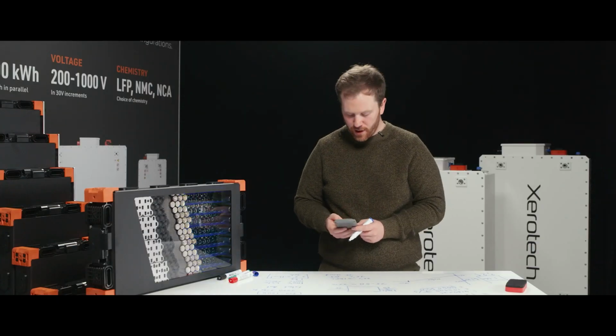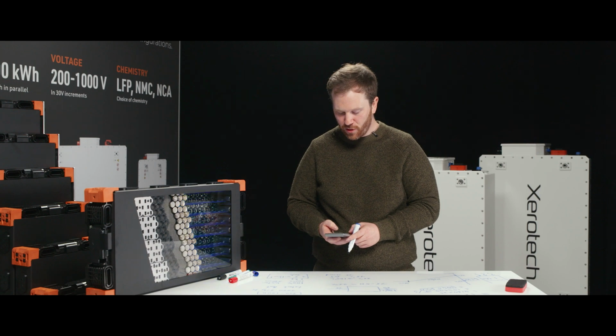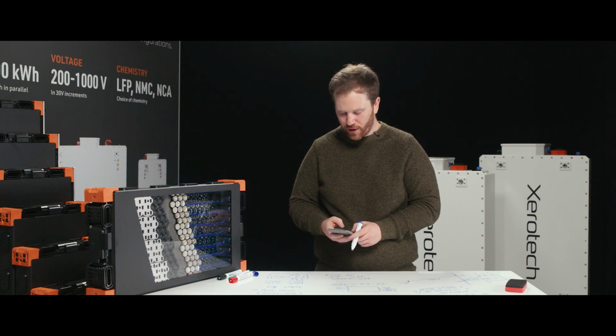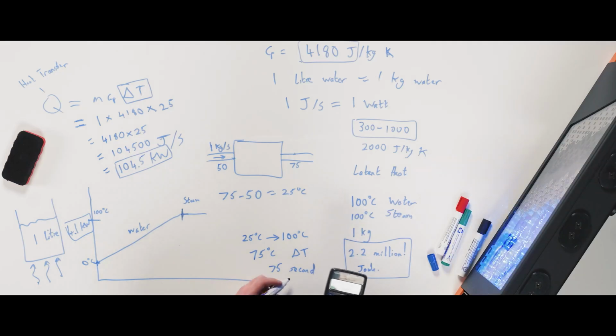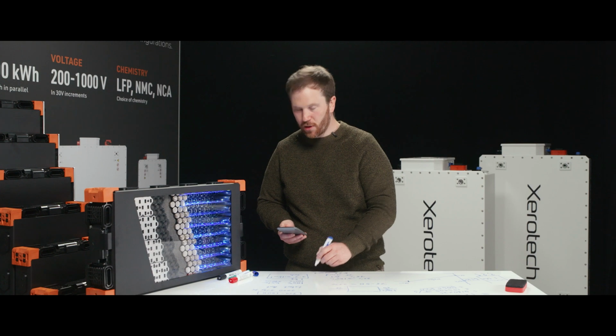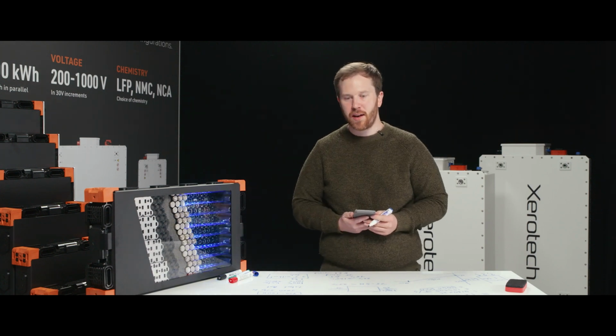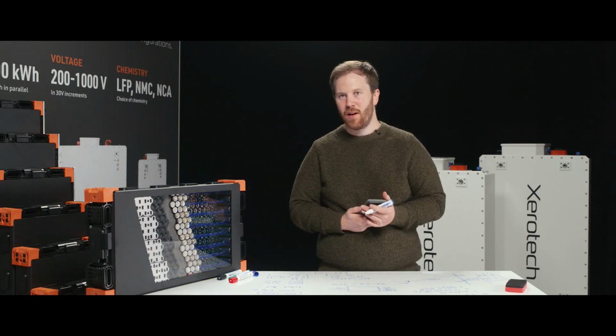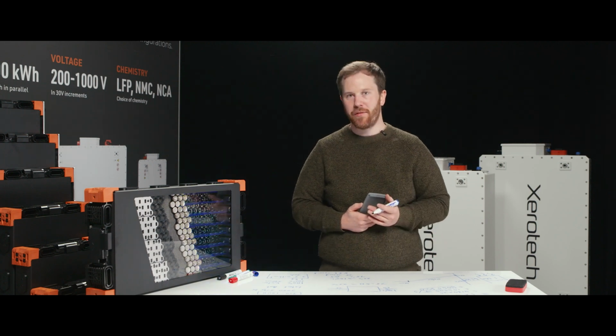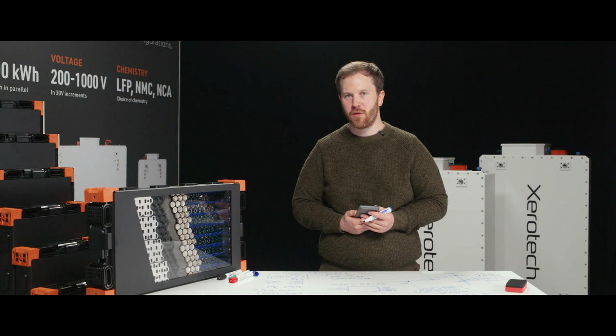So if you wanted to go from 100 degrees water to 100 degrees steam in our theoretical kettle here, it would take 2.2 million divided by 4,180. This would be 526 seconds, a much, much longer time. So you'd be standing there for nearly 10 minutes waiting for that all to convert to steam, whereas it only took about a minute to bring the water to 100 degrees C.